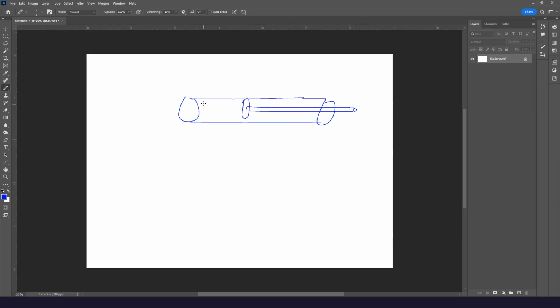If we supply air here, depending on the load and the force that needs to be applied to the load, that load can push back. Mr. Newton, there we go. Action and reaction. It's going to push back before it starts moving. So the air, because it's compressible, is going to have some kind of delayed reaction.